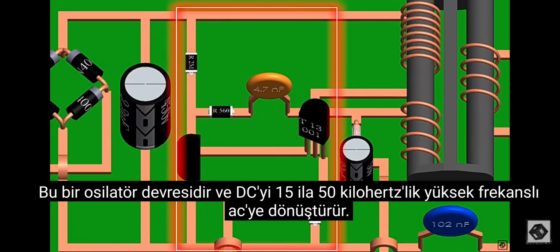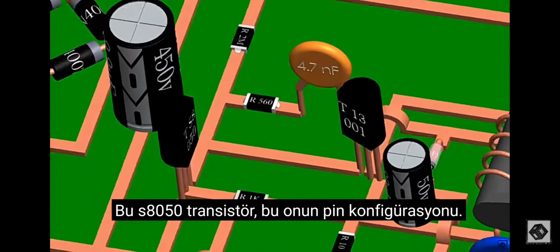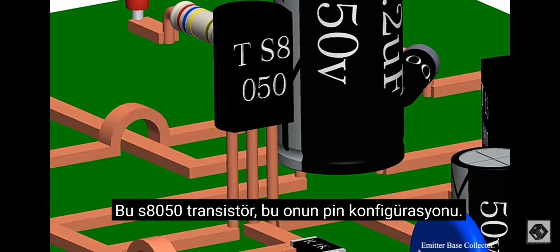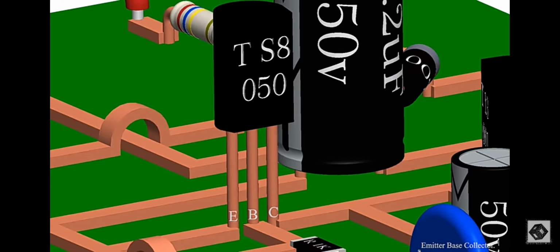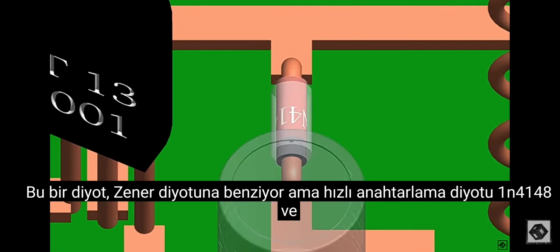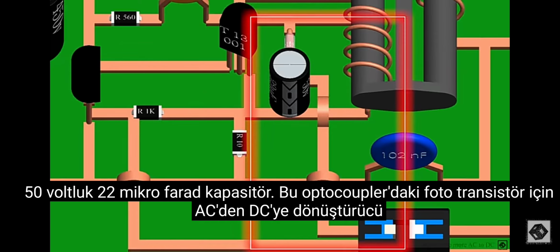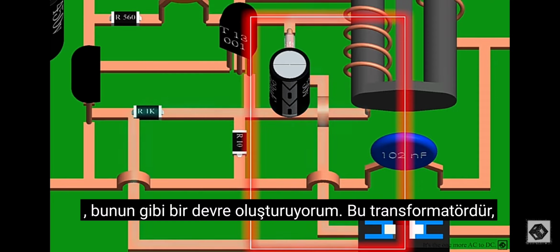This is an oscillator circuit. This converts DC back to high-frequency AC of 15 to 50 kHz. We can see the values of the components. This is transistor S8050. This is its pin configuration. And this is transistor 13001. This is its pin configuration. This is a diode. It looks like a Zener diode, but it's a fast-switching diode 1N4148 and a capacitor of 50 volts 22 microfarad. This is an AC to DC converter for the phototransistor in the optocoupler. It forms a circuit like this.